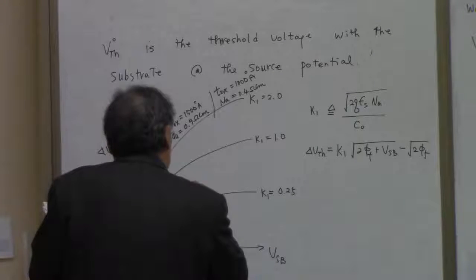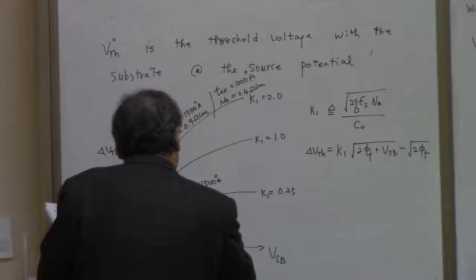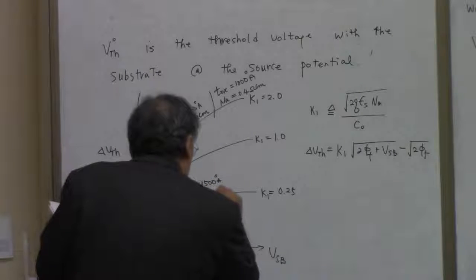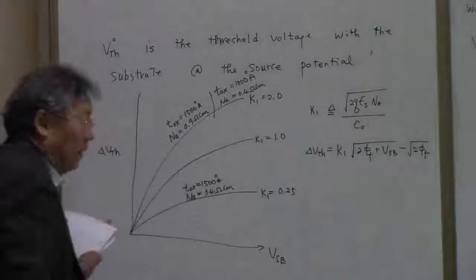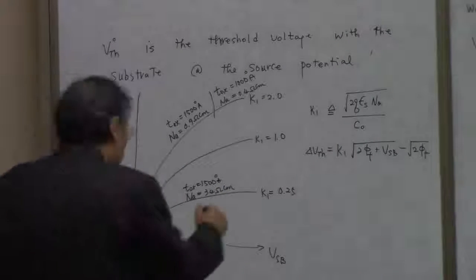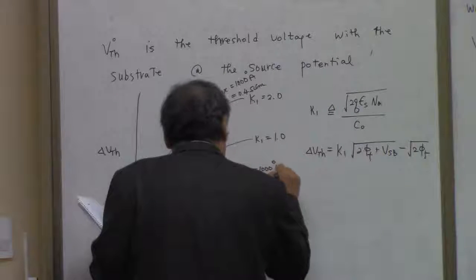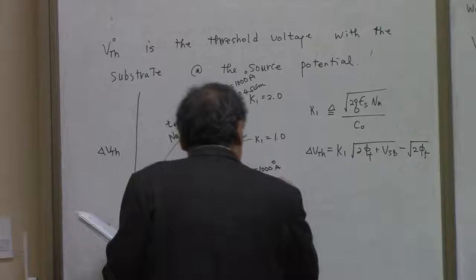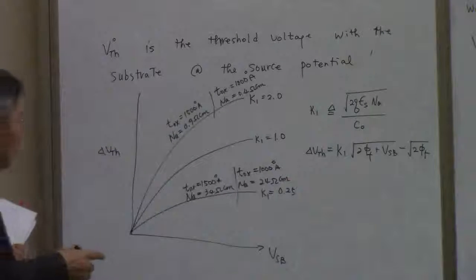You can reduce these factors by setting the same oxide thickness and reducing the substrate doping, like 34 ohm centimeter. Or if you keep the oxide thickness at 1000 angstrom, in this case you can have substrate doping like 24 ohm centimeter.